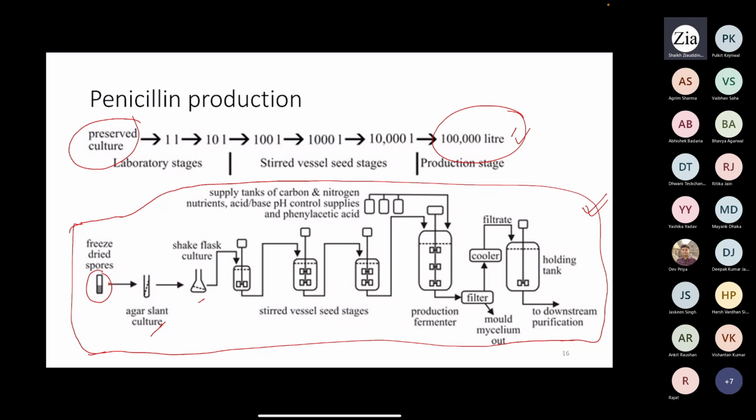In most cases, when you grow an aerobic culture, you always try to maintain 10% as inoculum. So when you use this shake flask, after growing the bacterium or fungal spore in the shake flask, suppose you are getting 500 ml volume, and this is a 1 liter reactor.